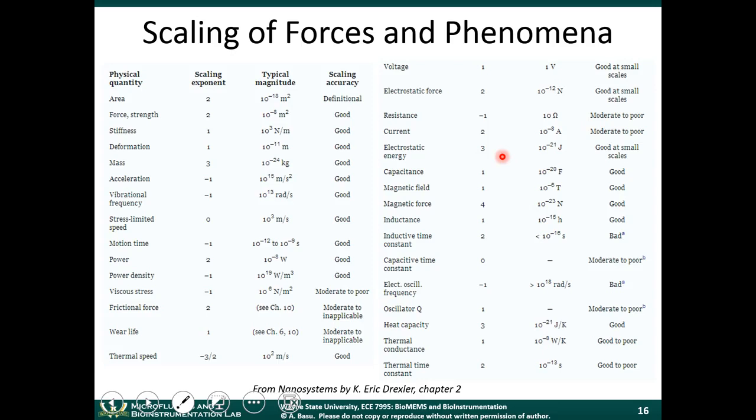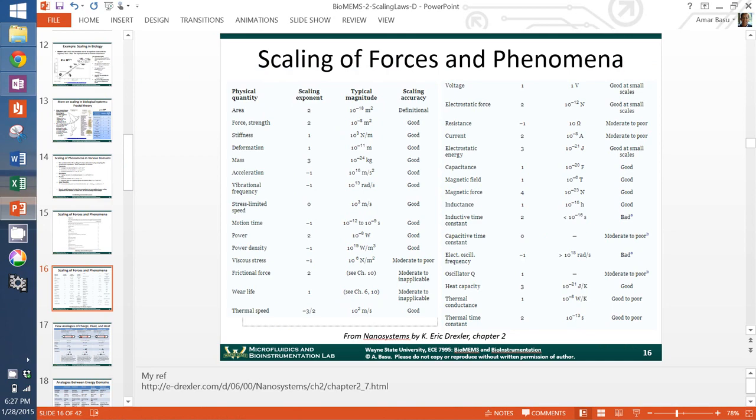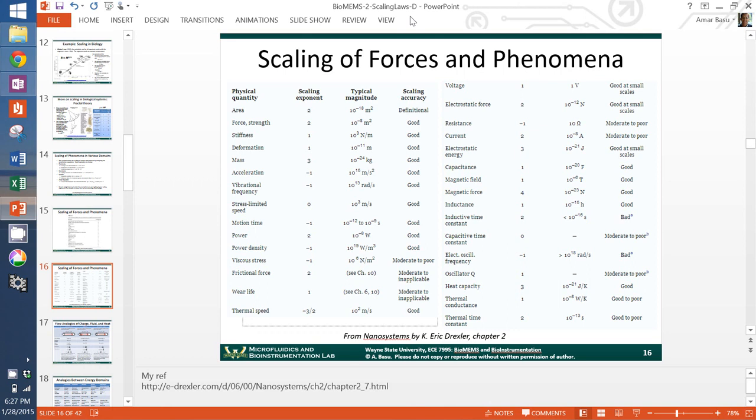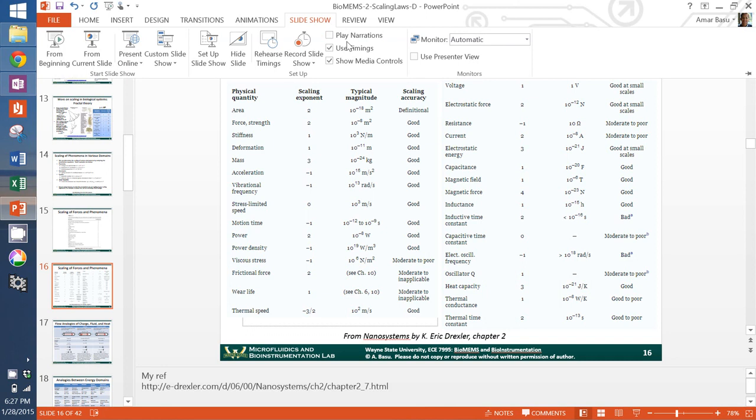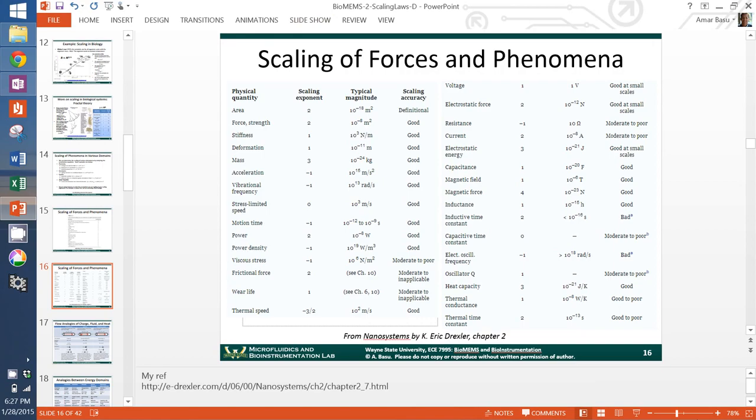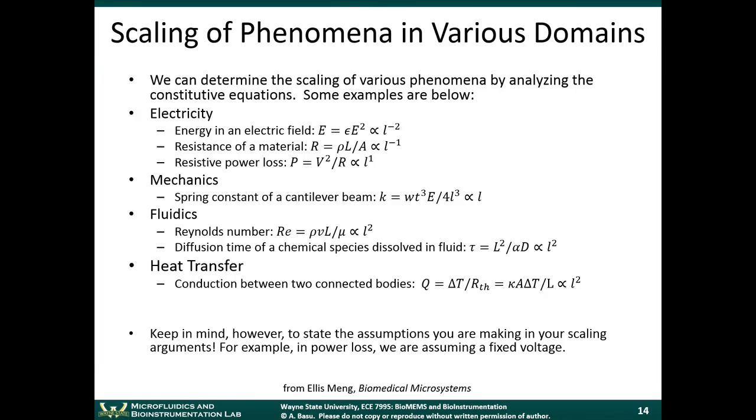Yes. I still have a question on the example you gave us on the spring constant, Hooke's law. Do you think that K has a direct proportion to L? Why? Okay, just a sec. The K is coming from this portion of the example here. In mechanics, the spring constant of a cantilever beam, K, scales as a length.